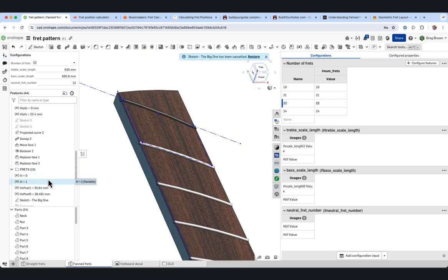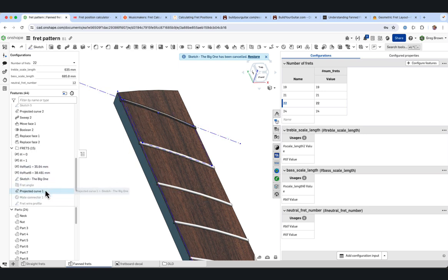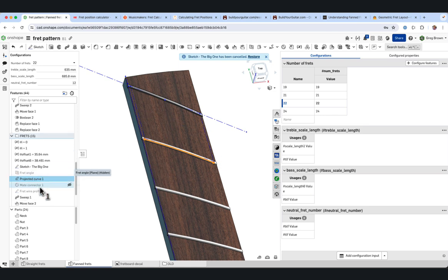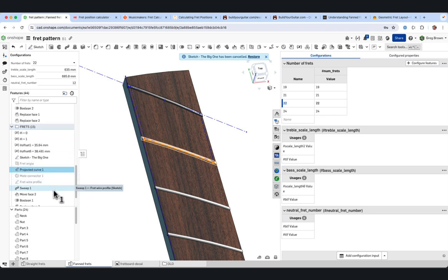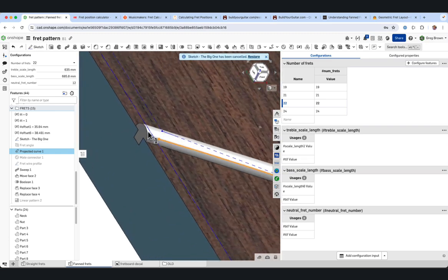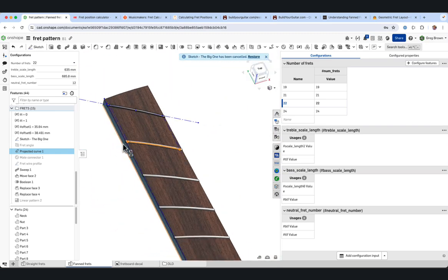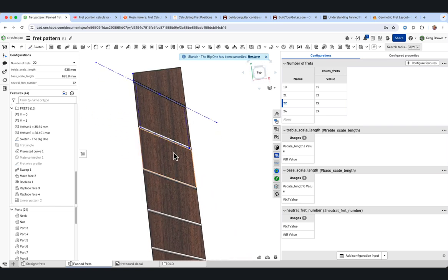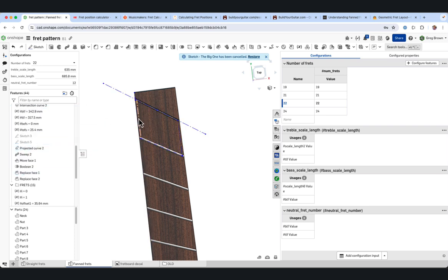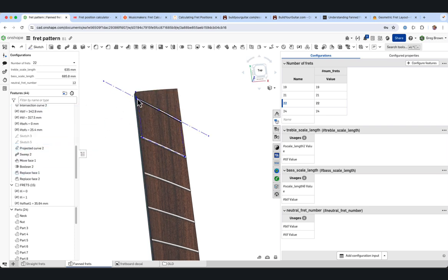The next thing I did after that was to project that sketch up onto this plane, and then did the similar sort of trick with a mate connector, a sweep, boolean. This time I did a replace face so that it's nice and flush on the sides. That is a lot of it, but there's some preliminary work that happened back at the nut, calculating. Before, we didn't have to worry about that. We just did a nut straight across and then measured one distance from it.